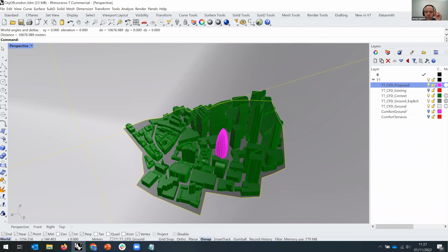Because this is ground, and we'll see this in a bit, it gets ground roughness attached to it automatically. So whether you set city or urban or suburban or open terrain, that gets attached per direction to this ground plane. I'm going a little bit into detail here, and I'm happy to share papers if people are interested in more detail. That is a representative average height of buildings. It's called the atmospheric boundary roughness length. So for urban terrain, that would be 0.8 meter, let's say.